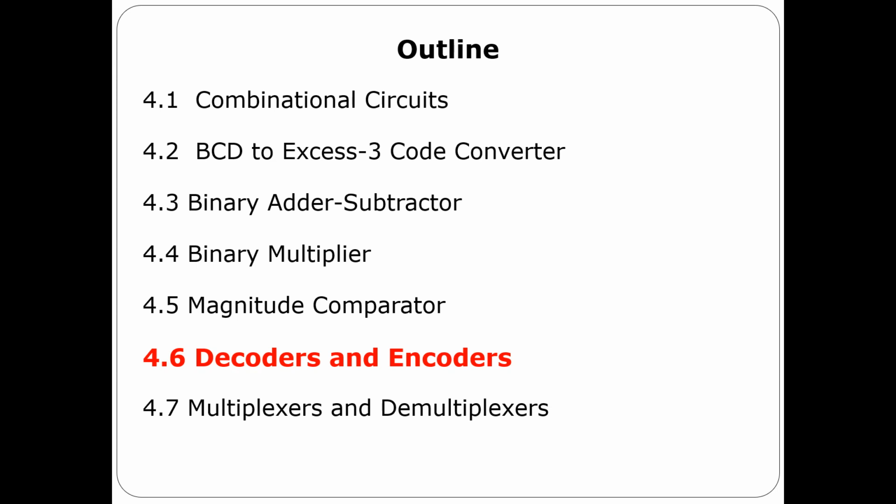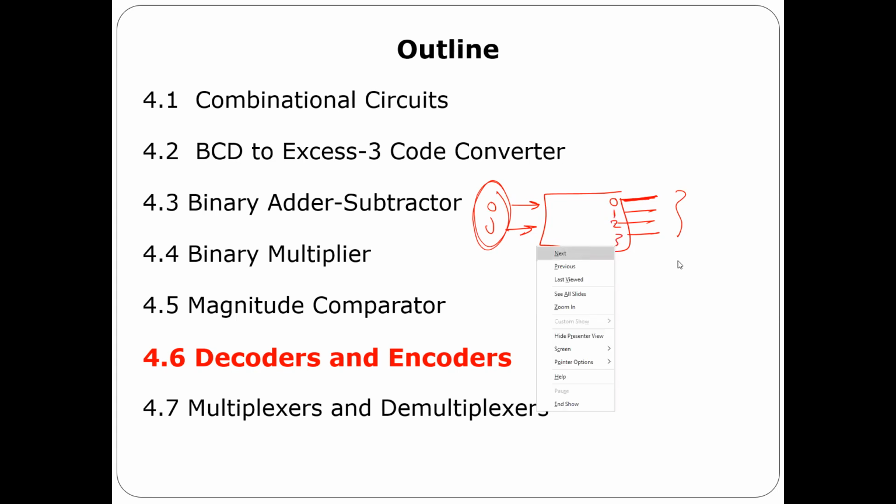Okay. So now I explained decoder. I told you in case of a decoder, if you have 2 inputs, you should have 4 outputs. That's what I explained. When the decimal value for the input is 0, this will correspond to this output here. So the outputs 0, 1, 2, and 3. Always one of them is 1, and the others are 0. So if the input is 0, output number 0 is 1 and everything else is 0. If the input is 3, output number 3 is 1, and everyone else is 0. This is how a decoder is.